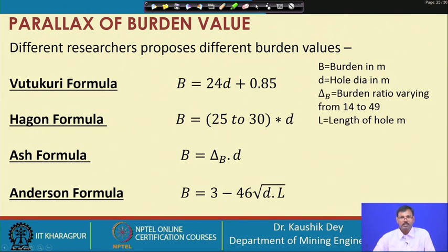In fact, I am not discussing the guideline which is given by Langefors and Kihlström for the large diameter holes, because obviously 165 mm is not the end of the drilling diameter. Presently, we are using 350 mm diameter drill holes also. So, large diameter holes are also there, and they are used for different blastings. That guideline is also given by Langefors and Kihlström in their book, but because of the time constraint we are not showing it in this lecture, but I strongly suggest you must go through all those guidelines in your further study.